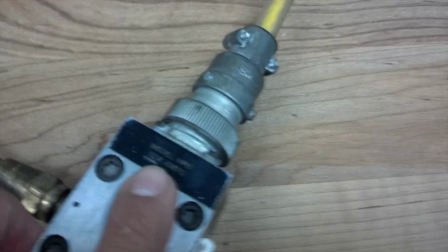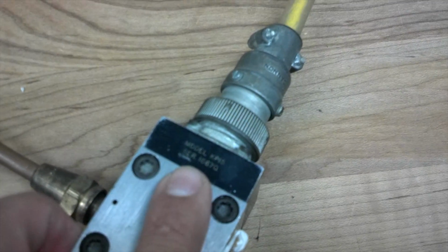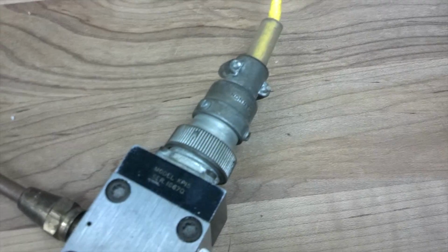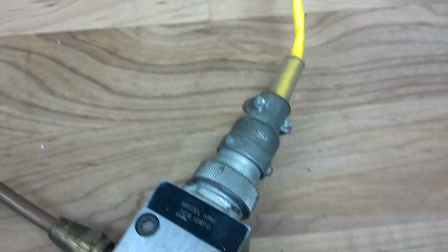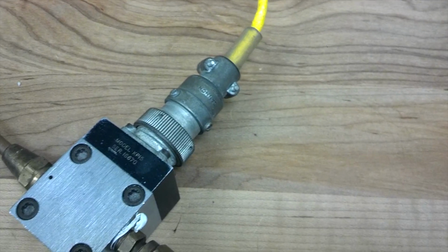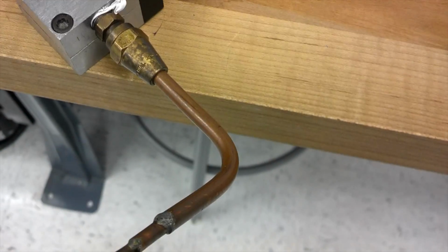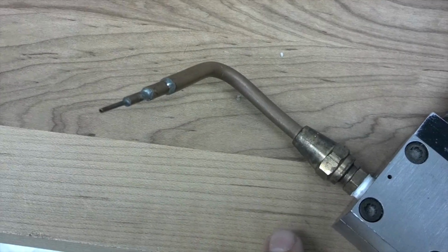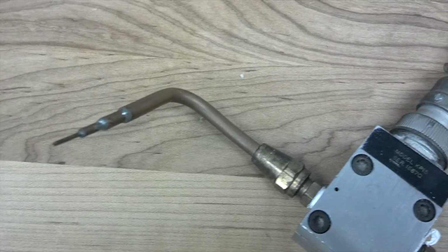This is a Pace Engineering Company KP15 pressure transducer. This particular one has interchangeable diaphragms, but for this experiment, a diaphragm rated up to 1 psi differential pressure is used. The transducer has a stagnation pressure port that we are using to link to the pitot-static tube to receive airflow. The transducer also has a static pressure port that we are using to detect the atmospheric pressure. In our case, it is linked to the top port of the pitot-static tube.